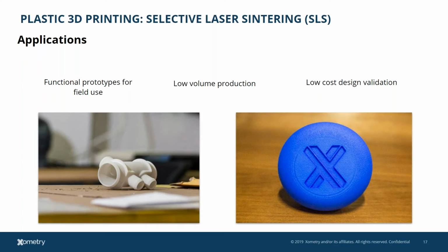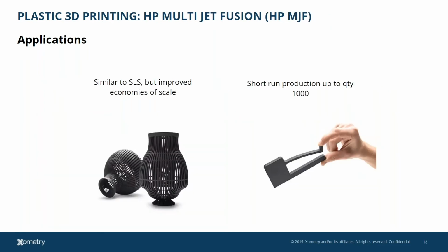It builds parts in a nylon powder bed without the need for support structure. You can stack parts in the X, Y, and Z direction and literally float them in your build, so you have a high throughput for this. It also makes the per part price cheap, and the lead times usually are pretty quick, starting at about 3 business days or so. You can see that matte grainy finish we talked about, and you're also looking at pretty good detail resolution, not super crisp on small features, but pretty good for the most part. So SLS is kind of my 85% tool. 85% of the time when I'm looking at a 3D printing project, I will probably start with SLS nylon.